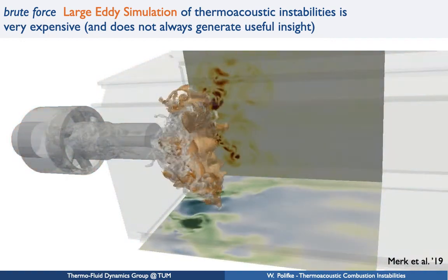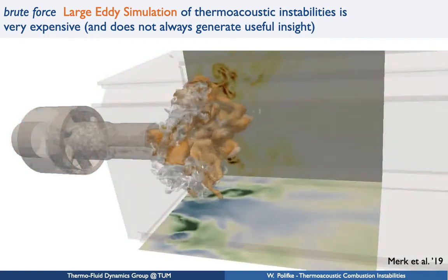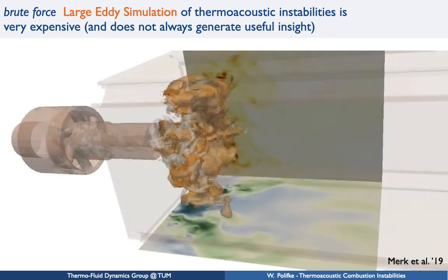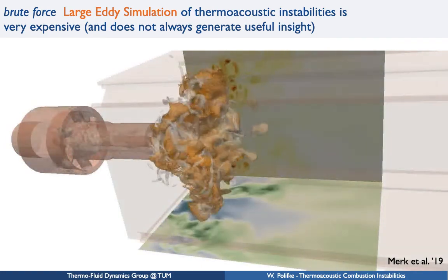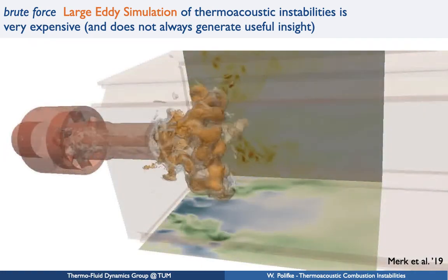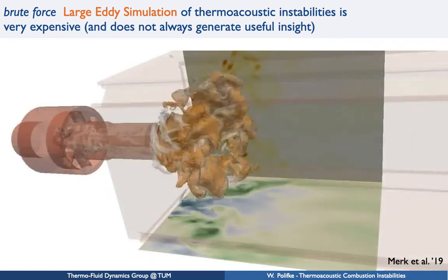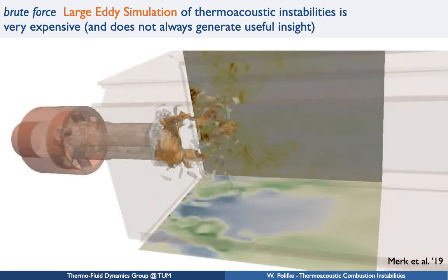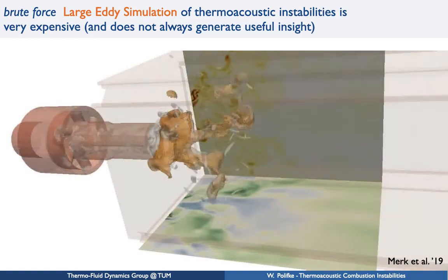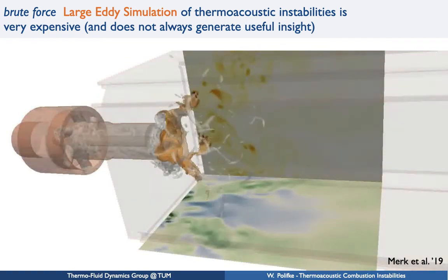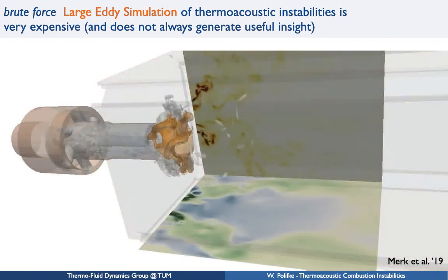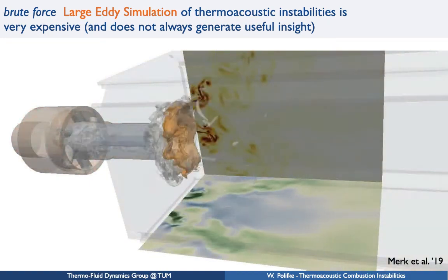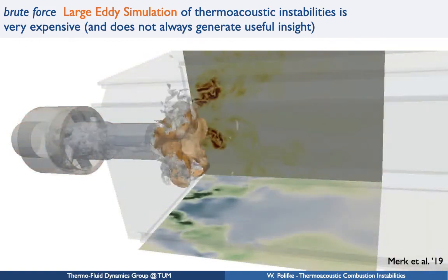This is turbulent. Also you see these wormy structures which indicate vorticity, vortical structures, and the orange surface indicates areas where burning actually happens in this flame. So you see it's a terribly complicated phenomenon, lots of small-scale activity. You see a pulsating behavior here, which results from the thermoacoustic instability. But on top of this overall pulsating behavior, you also see a lot of small-scale activity, which is a result of the fact that we have a turbulent flow here.